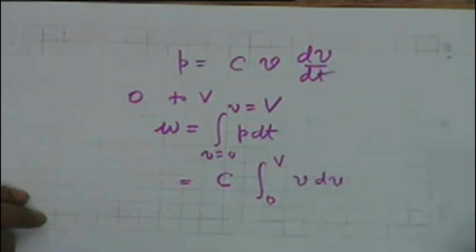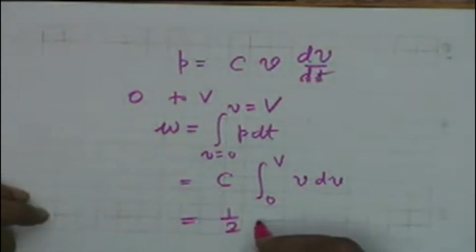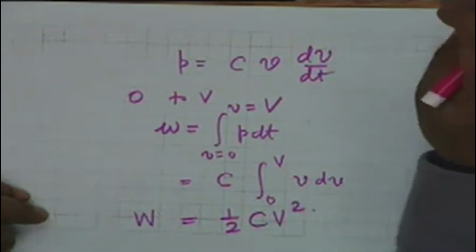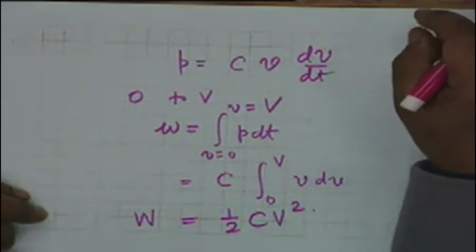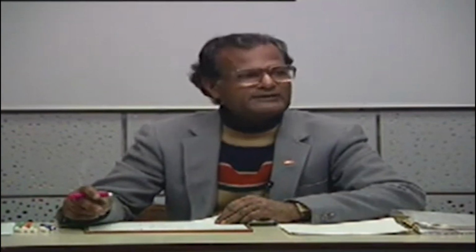dt and dt cancel, the rate of change with respect to time, and therefore the energy stored in the capacitor is half CV squared. Why is it stored and not dissipated like in a resistor? Because this energy can be extracted, can be recovered from the capacitor. If you leave the capacitor after charging to a voltage capital V intact, if you do not disturb it, it shall maintain its charge for time immemorial, time ad infinitum, and therefore this energy can be recovered.